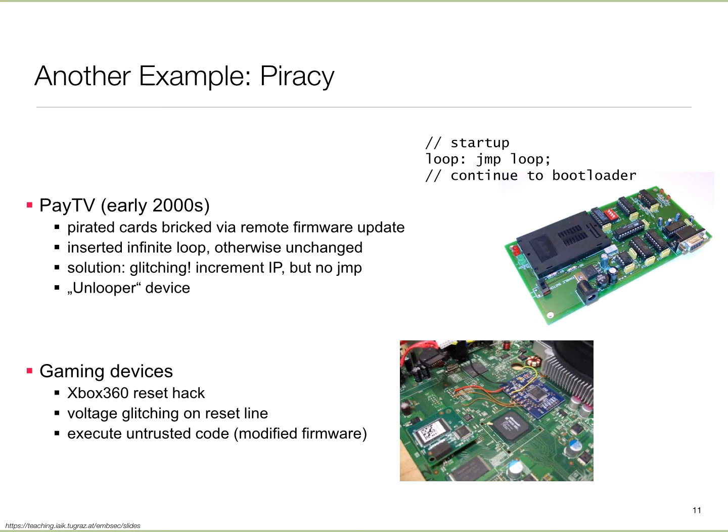Piracy, I already mentioned that, breaking into cable modem boxes, gaming devices, stuff like that. So all sorts of side channels get probed and exploited in this. Oftentimes, interesting things can happen to these devices when they are resetting. Another modality which people often use is that you deliberately induce a glitch in the power supply. The device is operating, but you cause a glitch in the power supply, and the way the device reacts to it reveals a lot about its behavior.